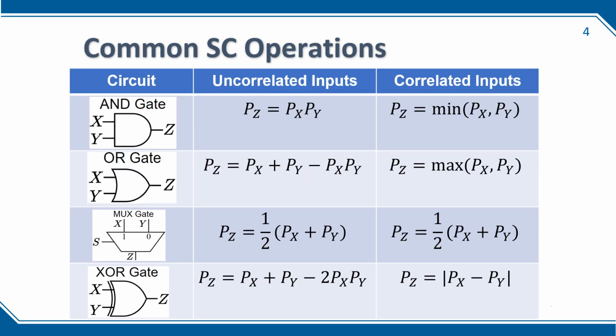Circuits operating using stochastic numbers instead of binary tend to achieve better area and fault tolerance at the cost of lower precision and higher latency. For instance, a single AND gate multiplies the input probability values when the input bit streams are uncorrelated. Compared with an adder-based binary multiplication circuit, the stochastic AND gate multiplier has substantially lower area.